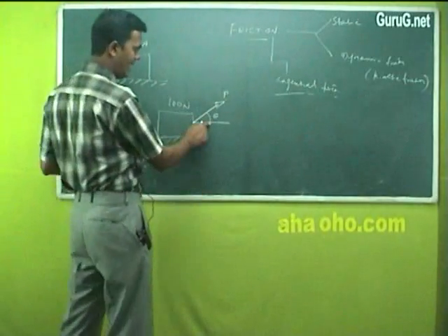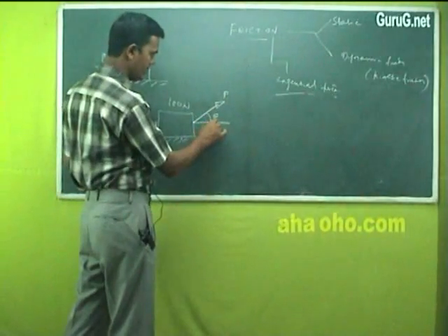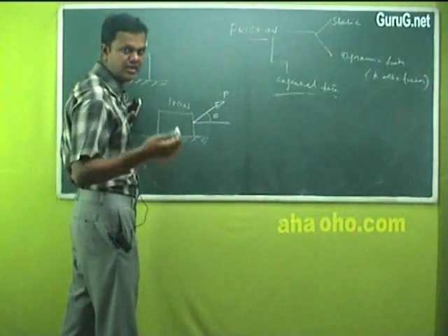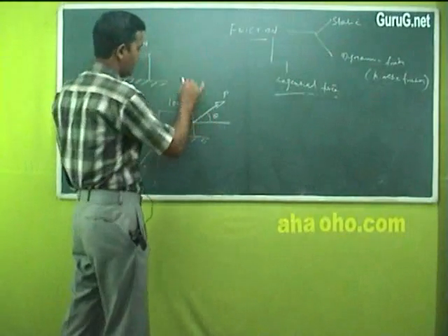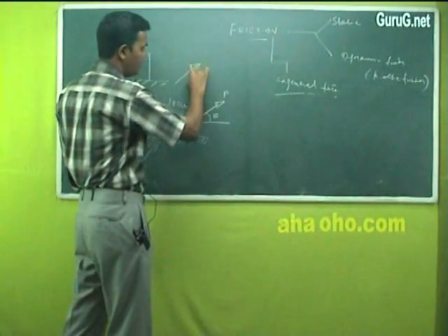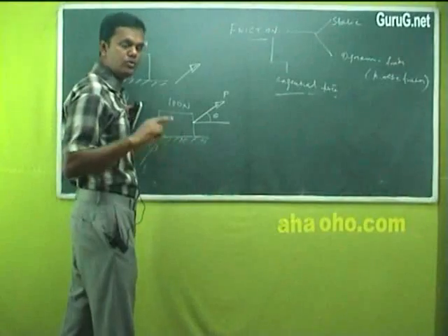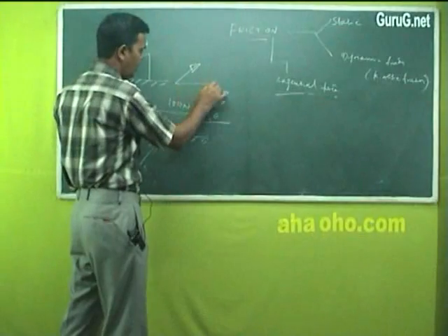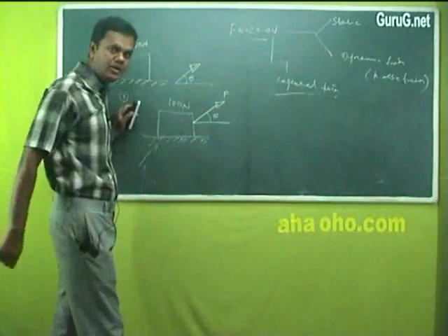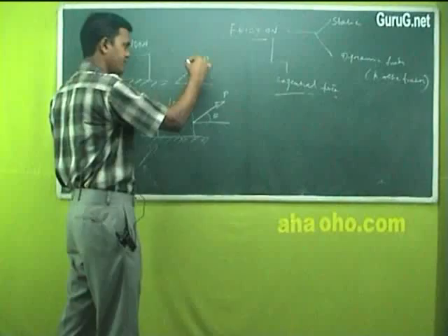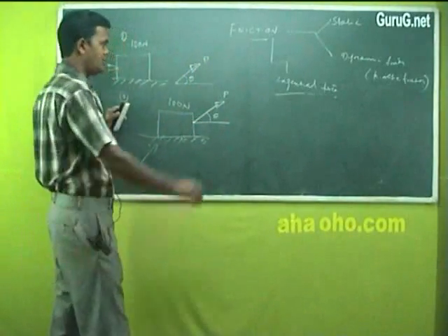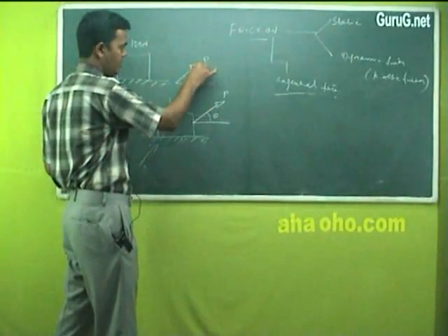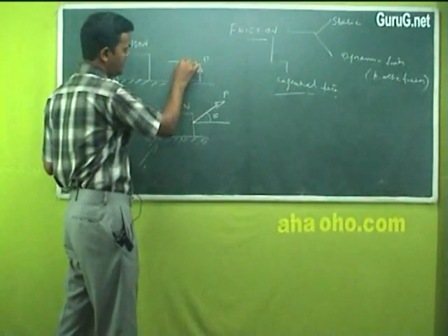Okay, and this angle theta, when a force is inclined, what is the basic idea? What we studied in chapter number 1? Any inclined force will have to be resolved into two components, one horizontal and one vertical. Is it not? Always we are bothered about an angle with the horizontal level. Suppose this is my force in an inclined fashion. I should obviously draw an arrow mark indicating this pointer with a vertical line as well as a horizontal line.